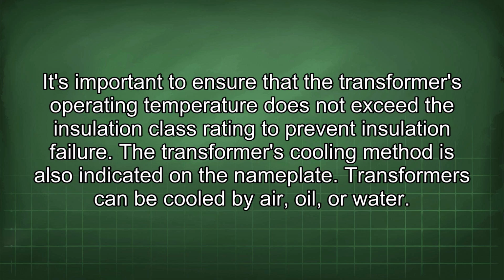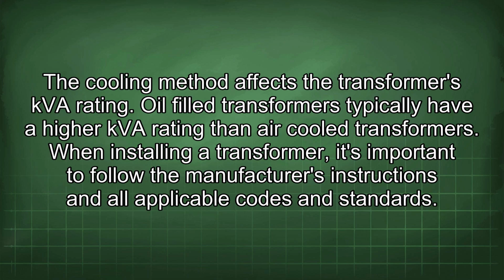The transformer's cooling method is also indicated in the nameplate. Transformers can be cooled by air, oil, or water. The cooling method affects the transformer's kVA rating. Oil-filled transformers typically have a higher kVA rating than air-cooled transformers.